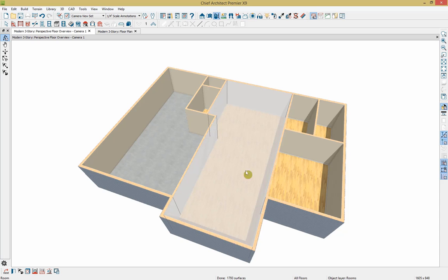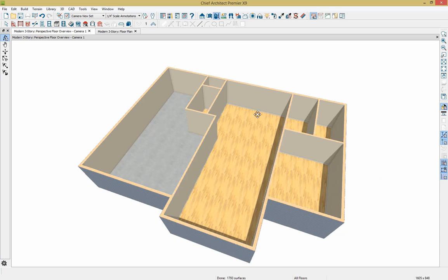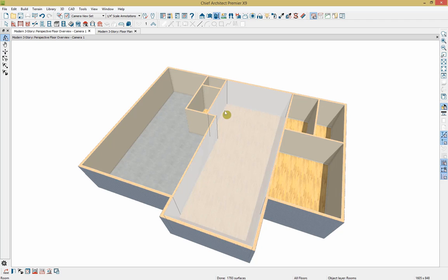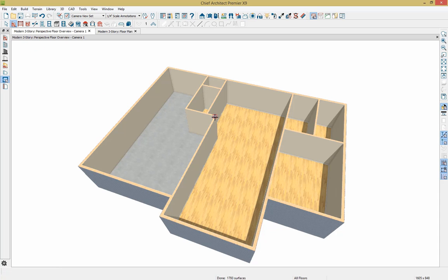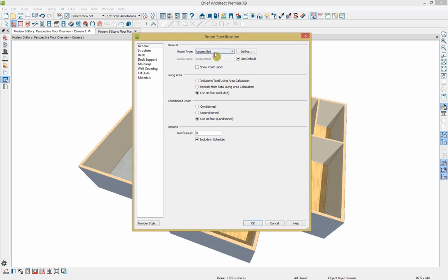And in this space, I'd like to put a kitchen in this back area, and I'd like to have tile there, but have it open to the rest of the space. So when I select it and want to modify, the entire space is selected. So what I can do is use my room divider tool and just click and drag out a room divider, and now I can single click in just that portion, and I'll open up our kitchen, change the name, and then you can also rename that if you want to have something a little bit different.